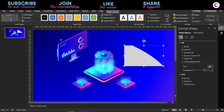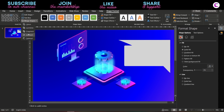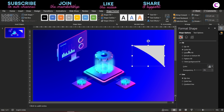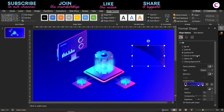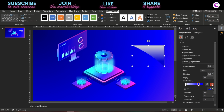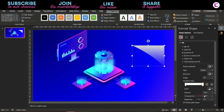Now select both the shapes and click on intersect. Now fill the gradient color, and we need white color in our gradient stops, and we need only 2 gradient stops here. Add transparency on the bottom gradient stop,